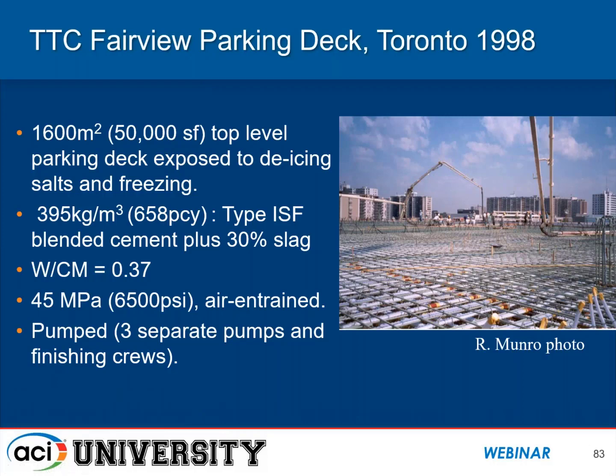One other example of a ternary mix for a parking deck, again going back over 20 years, was a fairly large pour with a blended silica fume cement and 30% slag. It was done in early July, well into the 90s Fahrenheit. There was a wind blowing, it was sunny, so all the things you need for plastic shrinkage cracking. But they pumped this concrete.